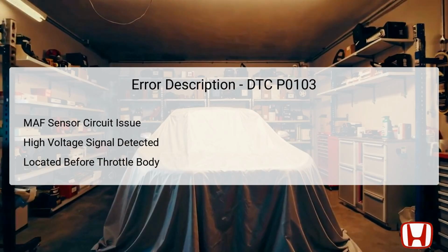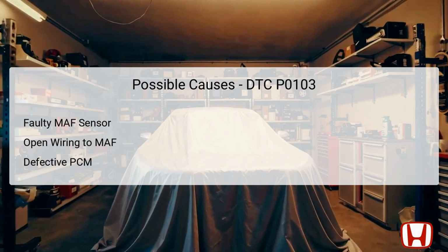If the MAF sensor circuit indicates high voltage, it may lead to rich fuel mixture conditions, which can adversely affect emissions and fuel economy. It's essential to ensure that the sensor is functioning correctly and that the circuit is intact to avoid further complications. Understanding the potential causes of DTC P0103 is essential for effective troubleshooting.